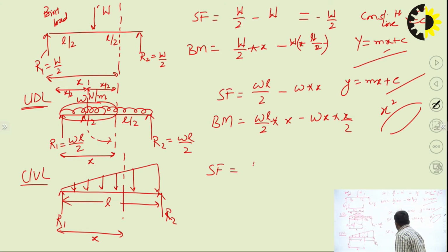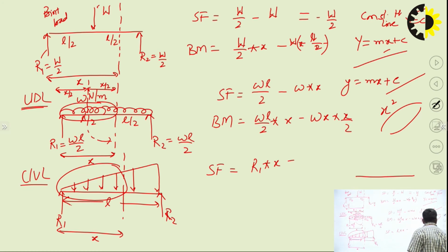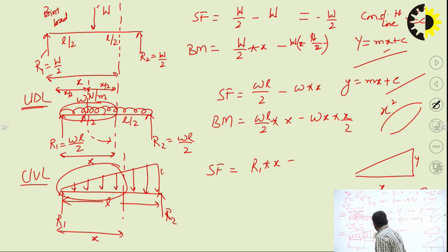Shear force equation will be R1 into x minus area of this triangle. Area of this triangle, how much it will be? मैं इसको लिख देता हूं, यहां पर अलग से ले लेता हूं. ठीक, this is x, this is what I am writing y, and पूरा ले लेता हूं, this is L, and here the intensity is W Newton per meter.